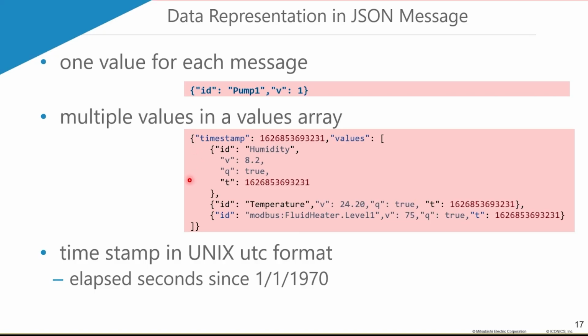And it is good to receive the quality data of the sensors and also the timestamp. Why is that so? Because having this quality and timestamp, we can use it to monitor our alarm management, we can see when this happens. It's not necessary, but we suggest including the quality and the timestamp in the message, right? And of course, the timestamp by default is always in UTC format, so we can always make changes inside our encoder, right?